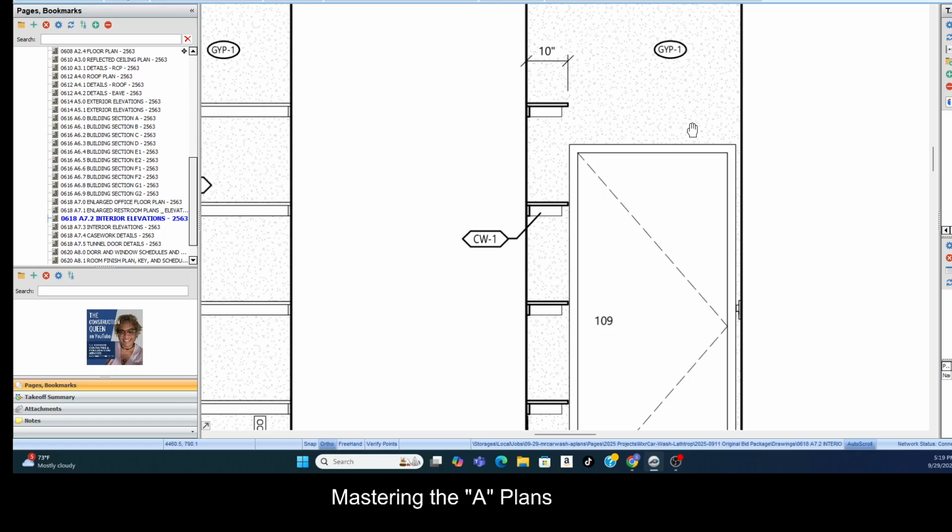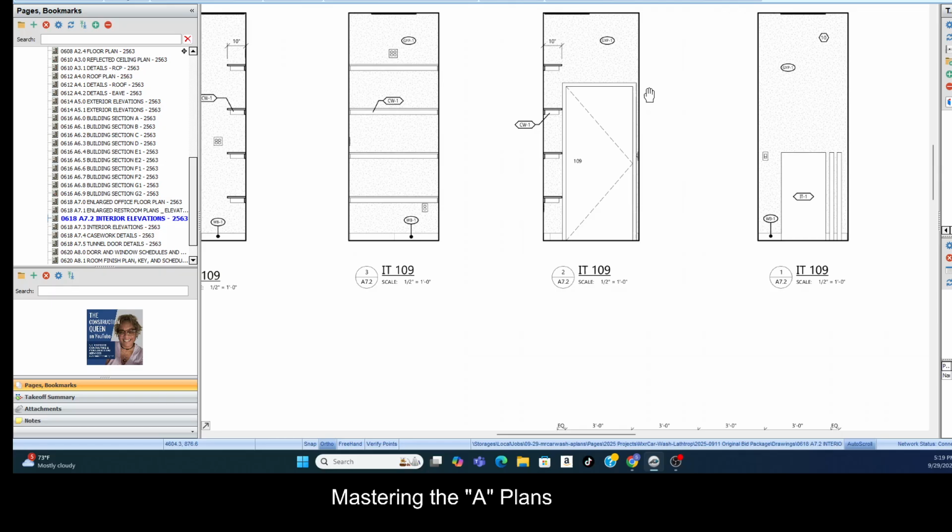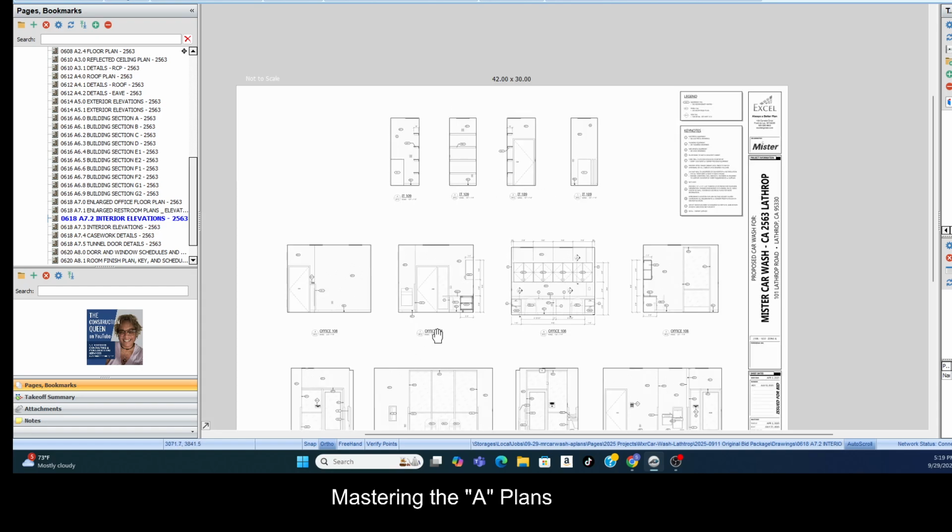It's not for the drywall person because their scope of work would be more detailed in the floor plan, but it's just telling you here that the finish is gyp and it's probably going to be painted. But we're going to look at the finish schedule, because the finish schedule is going to tell us what goes on each of the 4 walls and the ceiling and the floor per room. Okay, but just know interior elevations work just like exterior elevations. A room should have 4 sides, which it does, and each of the elevations reflects that room.